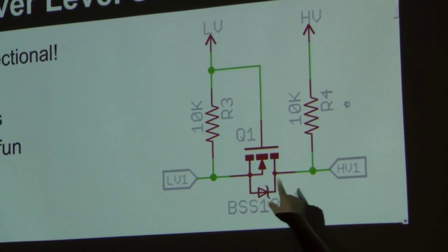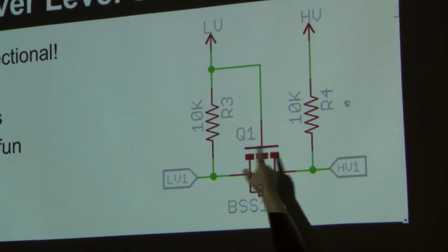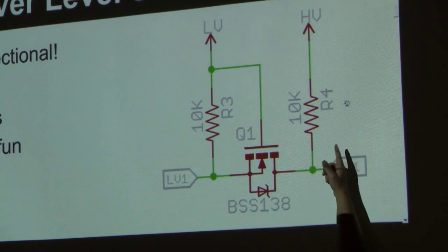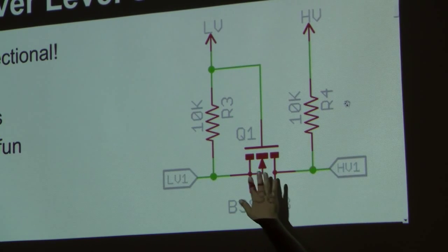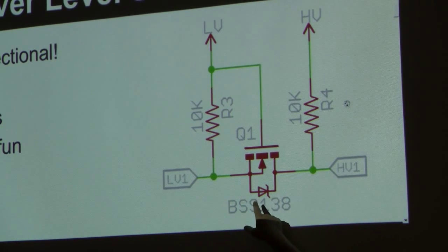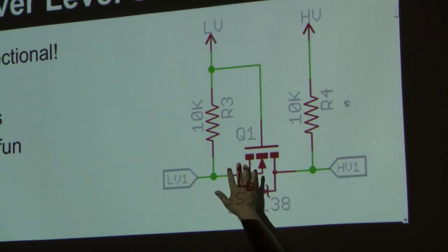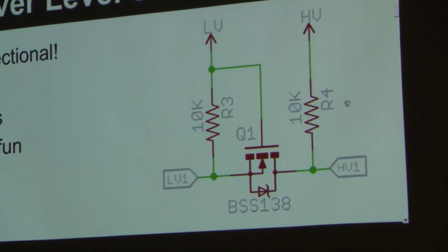The one thing that I thought would have been better about this is if they reversed it, because this is driving the FET with the low voltage as opposed to the FET's going to enhance better if you drive it with the high voltage. And if you flip it around, the lowest that this is going to be able to pull the low voltage down is the 0.6 volts, so you're going to have less voltage margin, where if you're using higher voltage logic over here, by definition, you're going to have higher margins. So I feel like it should be flipped and go the other way with the FET, but the circuit would work the same way. It would just shift the voltage favor over to driving the FET with a high voltage and using the 0.6 volt minimum 0 voltage on the high voltage side rather than low voltage side.